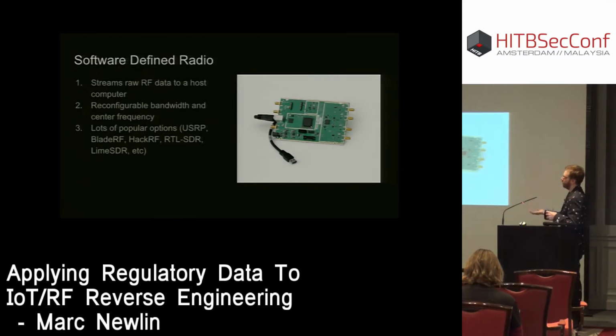And again, with the SDR, we can configure it to be whatever physical layer we want. So in this case, we can tune it to the specific frequencies that the mouse is likely to use and define using GNU Radio how we're going to demodulate the data.